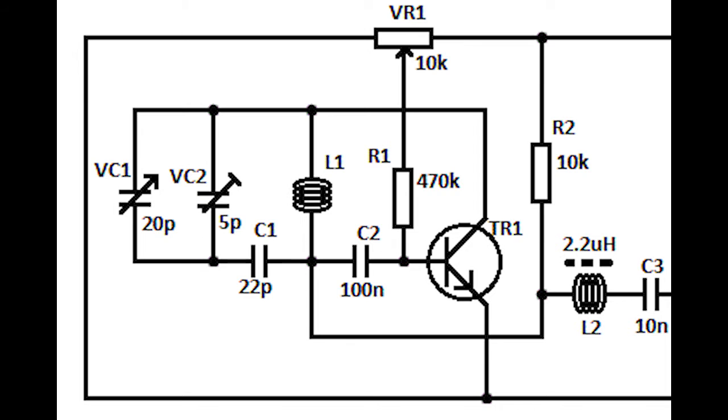Suppose you have to tune to a channel at a frequency equal to 93.5 MHz. So when you turn the knob to the 93.5 MHz marking, you are actually varying the capacitance of the LC oscillator circuit, that is, altering its resonant frequency. And as you alter the resonant frequency of the LC oscillator with the value of the intermediate frequency being fixed, you get the output after filtering, which was modulated on a carrier wave broadcasted at 93.5 MHz.